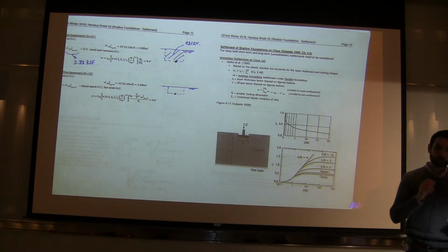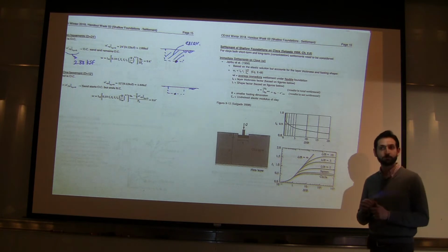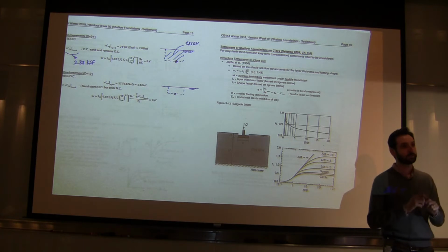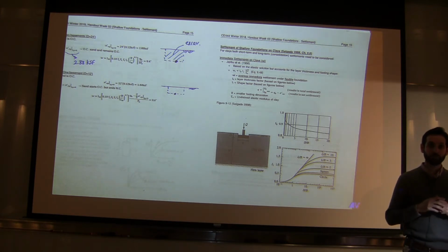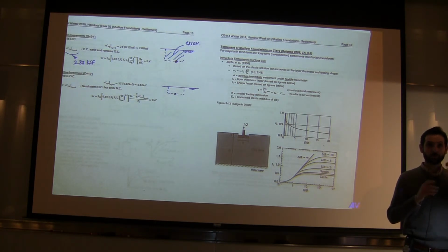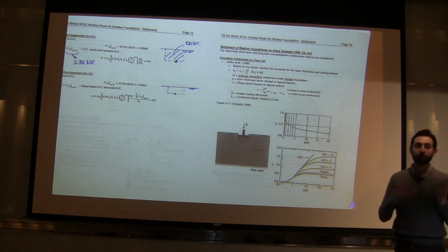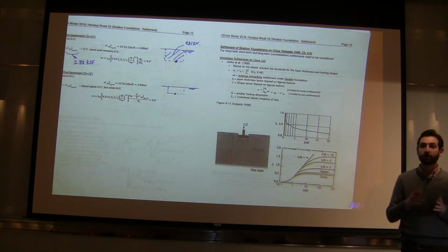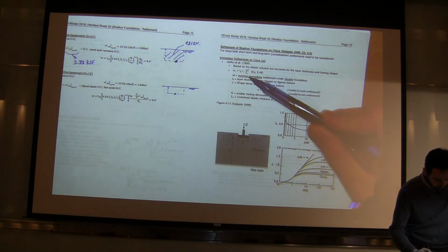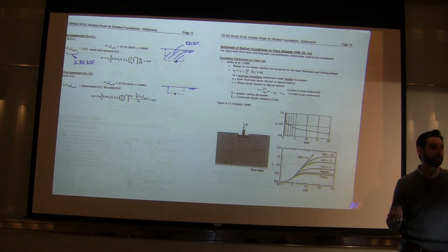Why does it have a U index? Undrained. Because when we start talking about clays, everything is undrained. Most of the loads that we are dealing with in analyzing clays are applied fast relative to the time it takes for the pore water pressure to dissipate in clays, so they're treated as undrained. That's why it has that U index. So we have to figure out a way to find the E sub u, or the undrained elastic modulus of clay.